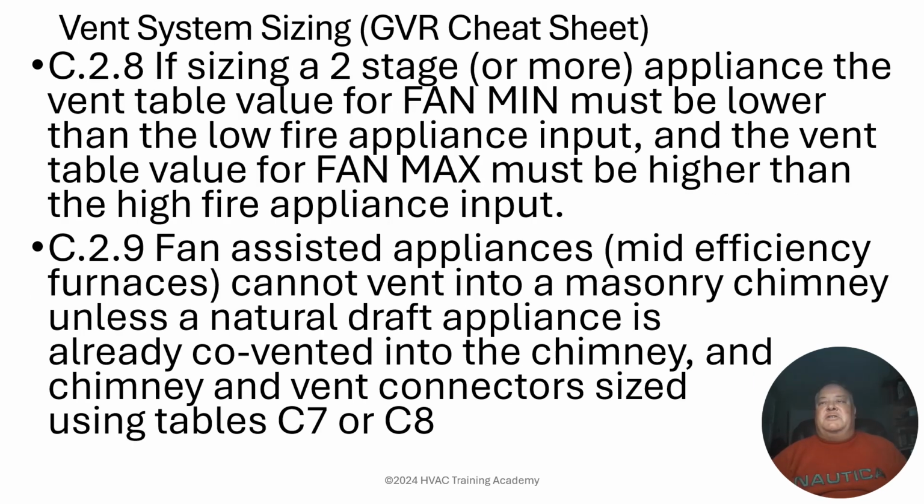You might be asking yourself some questions about common vent connectors. I'm going to go through all of that coming up as well. We talked about fan min and fan max, making sure our appliance inputs fit in between the fan min and fan max. Fan-assisted appliances cannot vent into a chimney unless a natural draft appliance is already co-vented into that chimney, and the chimney and vent connectors are sized using C7 or C8.